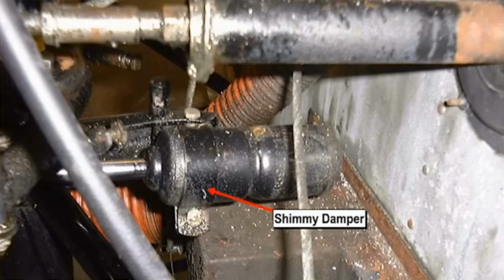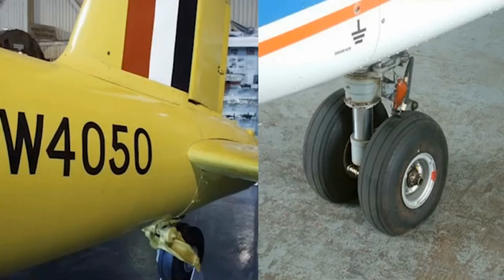Due to the flexibility of tyre sidewalls, an unstable rapid sinusoidal oscillation or vibration known as shimmy can be induced into the steerable parts of the undercarriage. Excessive shimmy, especially at high speeds, can set up vibrations throughout the aircraft and can be dangerous. Worn wheel bearings and uneven tyre pressures can both increase the tendency of the wheels to shimmy.